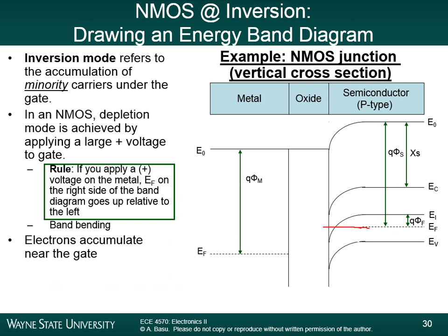So what does this mean? What does this mean in terms of carrier concentration? Out here, the Fermi level is close to the valence band, so it's p-type. And Hunte, you were saying? Yeah, at the interface it becomes n-type, because the Fermi level is now closer to the conduction band. Right? So you see this band bending actually converted the material from p-type to n-type at the interface. It's p-type out here, but at the interface it is now n-type.